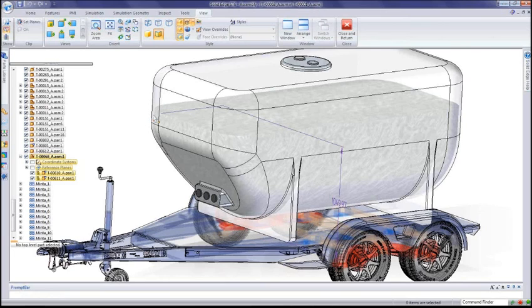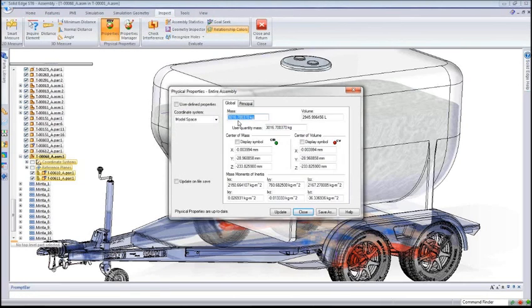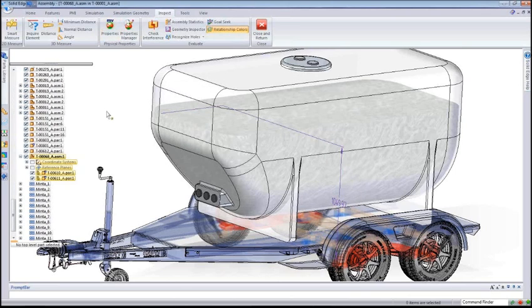What I want to do is use goal seek because I have a certain weight limit that can be pulled on this trailer, and it's approximately 4,200 pounds. If I were to go under inspect at this moment and check out my properties for this tank, at the tank level, I'm sitting here at 3,600 and, I said pounds, I should have said kilograms. And if I were to look at the update on this, just click on update, and yep, that's already updated. But wouldn't it be cool if I could say, I want to add in some more.